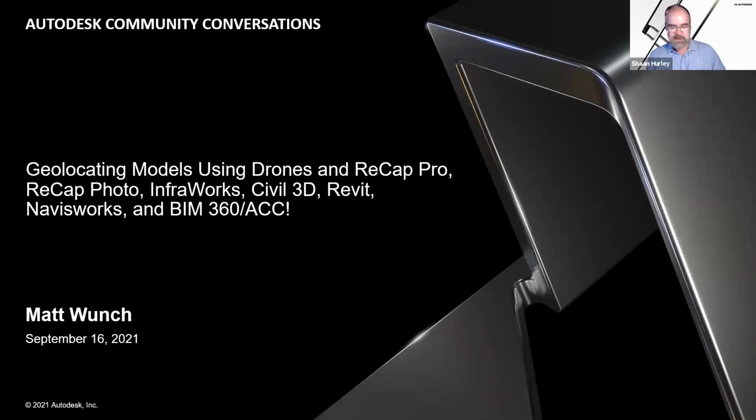But this is the type of model you're going to get to start with from InfraWorks Model Builder. Depending on where you are, you may have more or less information. In this case, it's a little bit of a rural suburban type area, so not a ton of, actually really no building information whatsoever. But I do get information regarding the roadways. So it knows that this is Raffia Road. It knows that this is Post Office Road. It knows all these different attributes associated with these objects. And you would get the same thing with major buildings, rivers, and waterways as well. So all this is coming from OpenStreetMap's data.